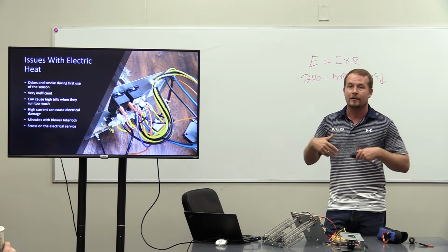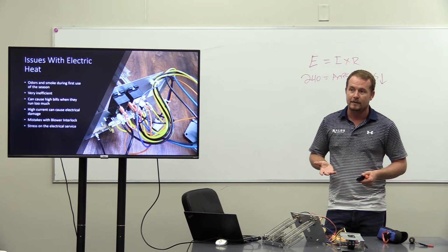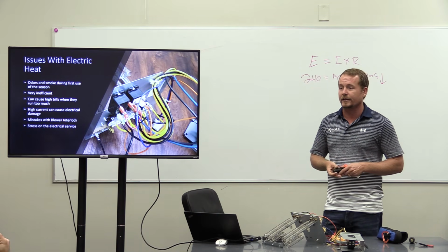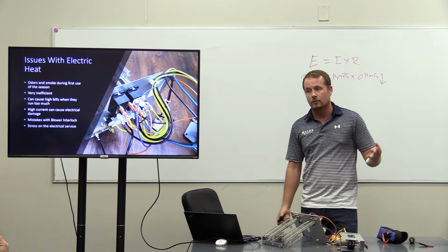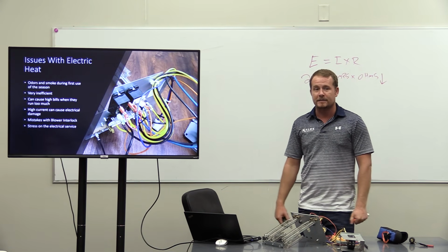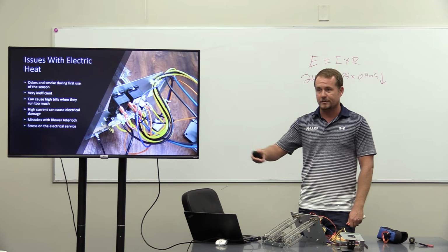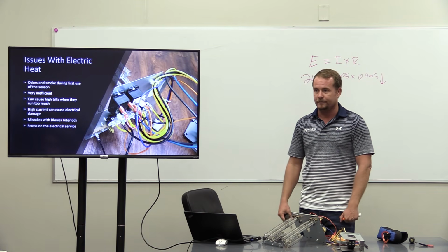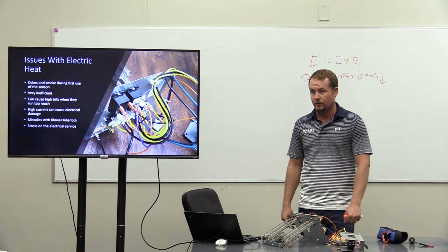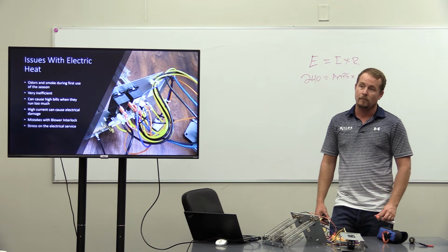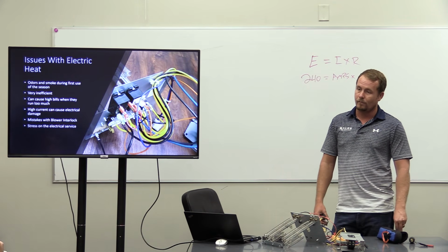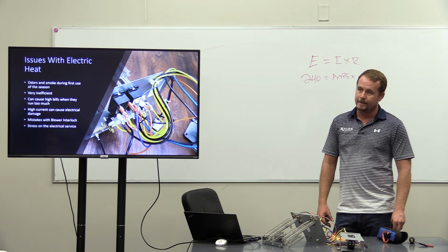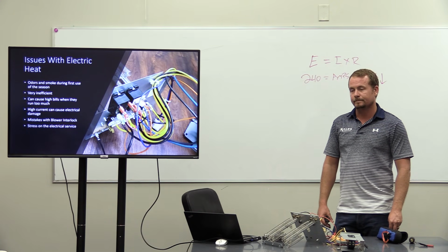That's the electrician's job. Well, if we're not calling an electrician out to look at it, or we're not thinking about it, then we could potentially overload the entire home service, which could be a potentially dangerous problem, especially in older homes that aren't wired very well to begin with. Maybe you have the old rag wiring or whatever, or aluminum wire, for example. You still have a 100 amp house where you probably wouldn't put above a 5 kW in anyway, but you've seen it with like a 10 kW.